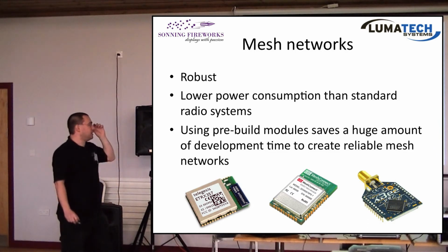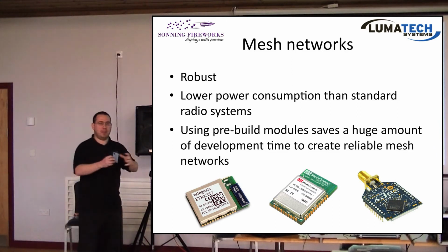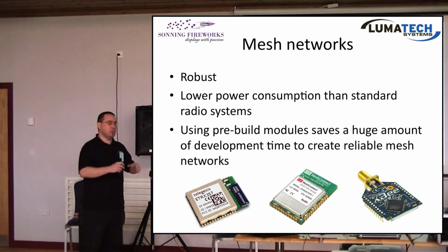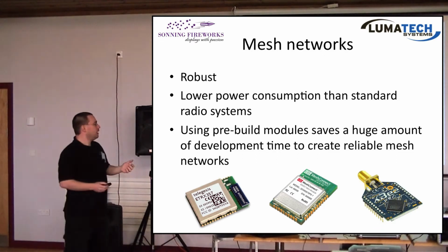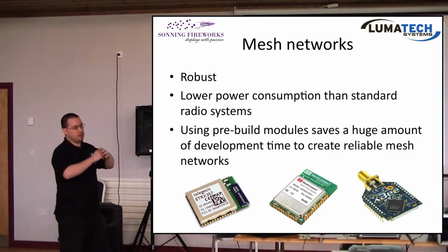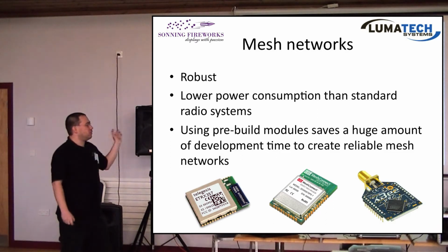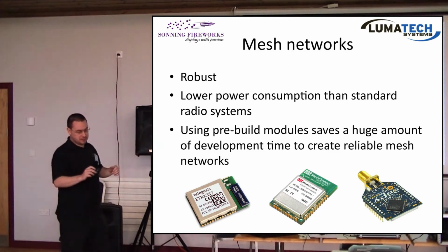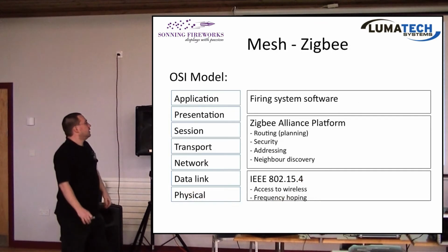They're quite low power consumption because you're not beaming out a ton of power from one controller. They can be more low power because they can relay their messages across. There's a lot of pre-built modules that people use for radio mesh systems because there's a lot of protocol in there to do all the fancy routing and mesh side. So there's lots of pre-built modules that people use, and you can just slap them in if you're designing a system, and use that to deal with all that part of it.